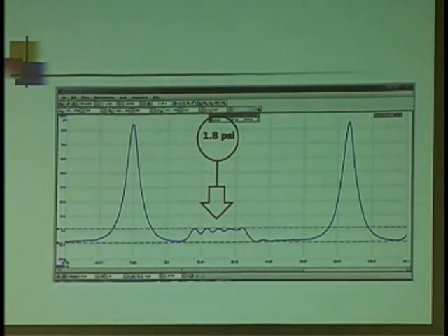Now here again, I'm measuring pressure. The exhaust valve is open. I'm heading back up towards TDC. I can measure this. This particular one measured 1.8 psi. Of course, I want to make sure my transducer is properly zeroed. But what am I measuring there? Spot pressure. Do you think I might be able to use this if I suspect a clogged cat? What if I have a dual cat system and I think one's messed up and the other one isn't? Could I compare bank to bank?